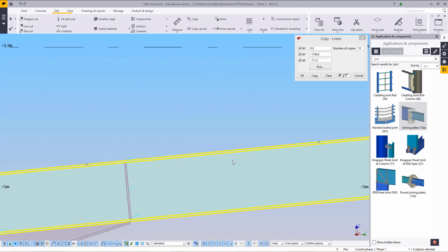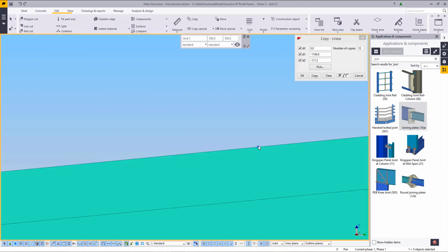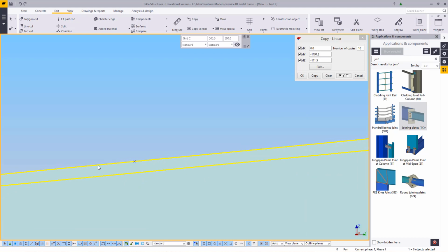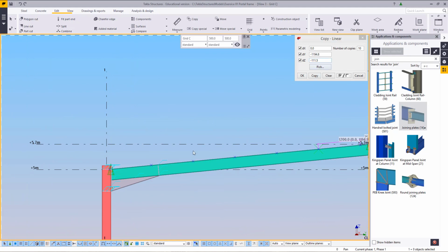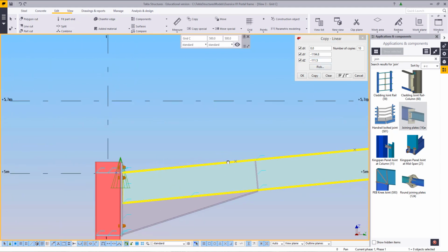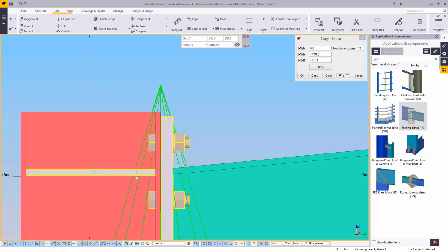Again, you might just want to zoom into a couple of spots and make sure that the point is still on the top line of your rafter. If you did your angle slightly wrong when doing this, they will no longer be on the rafter and your roof will not be aligned properly.